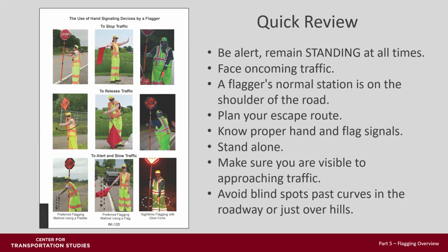Let's do a quick review. Be alert, remain standing at all times. Face oncoming traffic. Never fully turn your back to oncoming traffic or stand in the path of moving traffic. The flagger's normal station is on the shoulder of the road. Plan your escape route. Park your vehicle off the road away from your station. A flagger is difficult to see when they're next to a vehicle. Never sit in or on your vehicle while flagging.